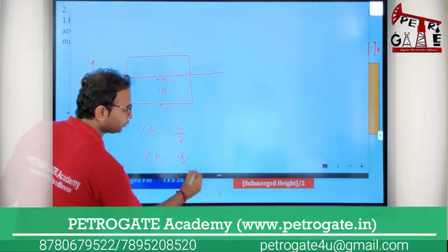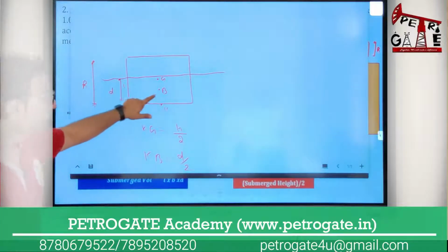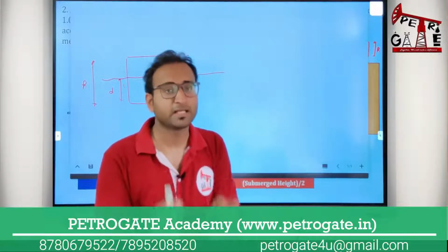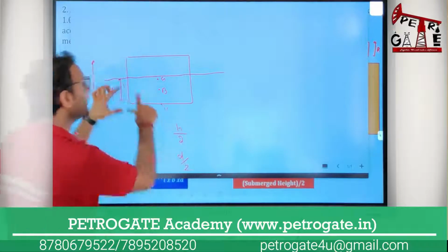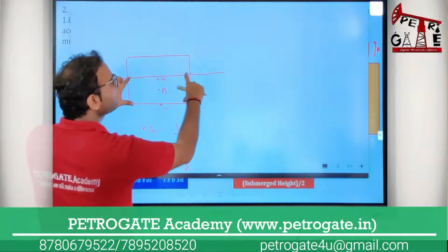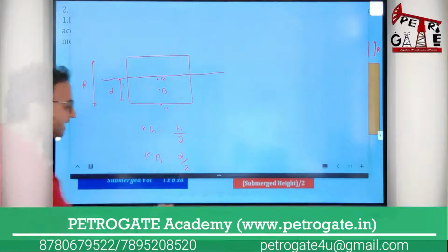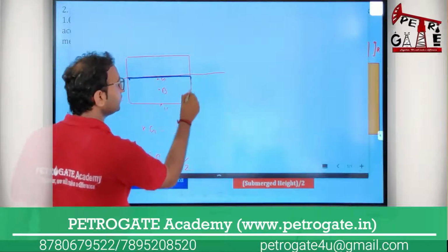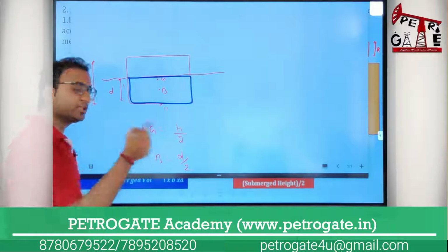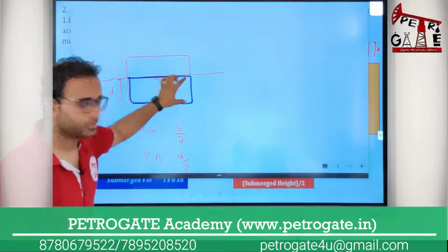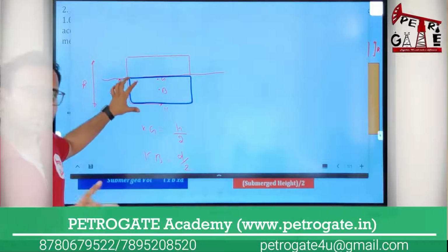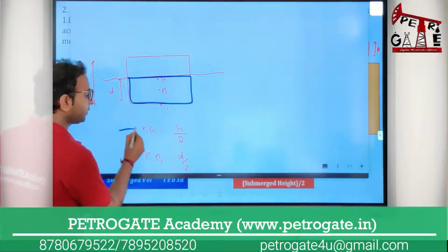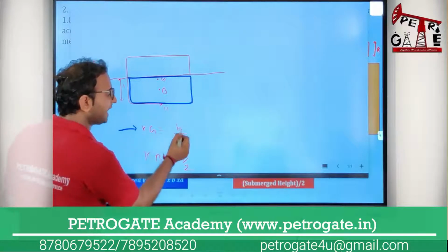So KG equals total height by 2, and KB equals submerged height by 2. The center of buoyancy is also a center of gravity, but only of the submerged height, only this particular part of the object. The normal center of gravity is for the total object. That's why I am telling you center of gravity equals total height by 2.